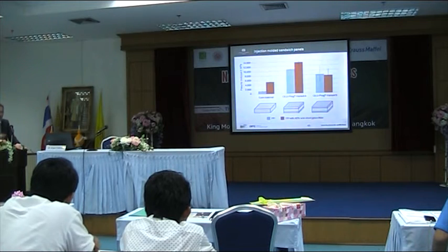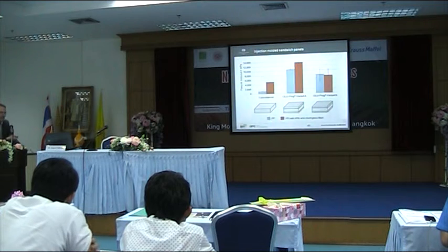So it's the local reinforcement. You have to look at which forces you have in your part. The local reinforcement here is made for sandwich structures, for bending stiffness. You can achieve really good mechanical properties.